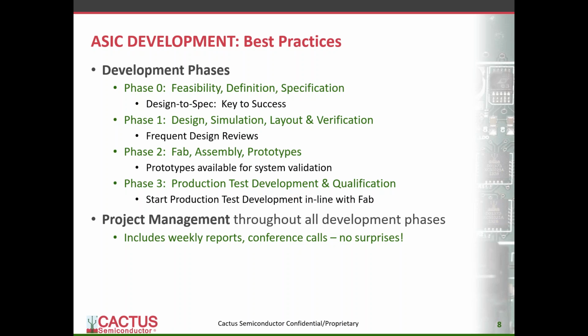And finally, phase 3 is where we start talking about production. That's where we're going to do production test development. That includes software and hardware, as well as qualification, developing the hardware for qualification and running qualification, such as hot temperature op life, ESD, latch up, temp cycling, etc.